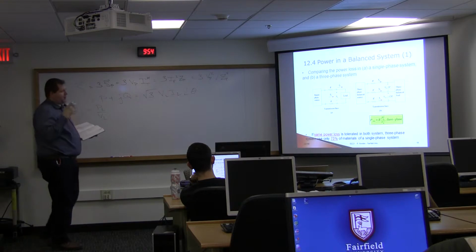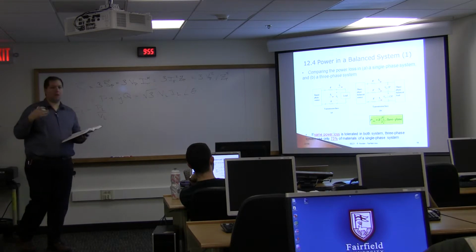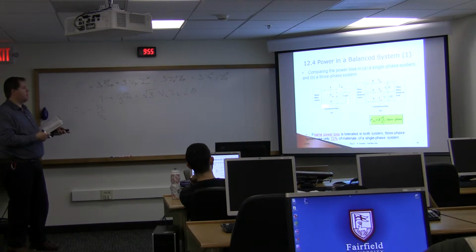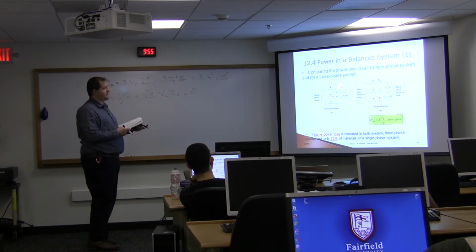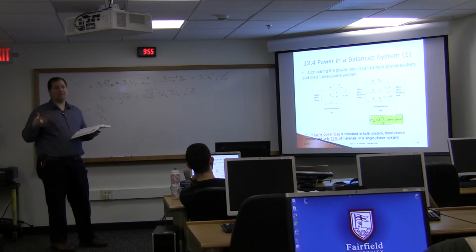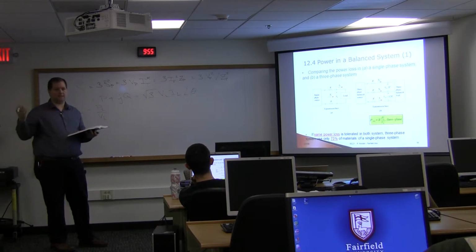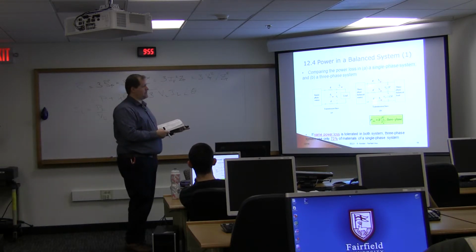Where this becomes powerful is, well, okay, big deal, right? However, if we're willing to take the same power loss, in other words, I calculate this and I lose 100 watts of power through this system. And the main thing that I'm really worried about is actually not so much the power in the load, although that does decide what current flows, but the power lost in the line itself. So that's really what we're looking at. So this R, which is the resistance of the wire, is the power loss. That's wasted.